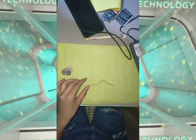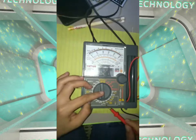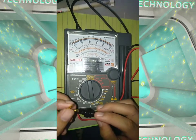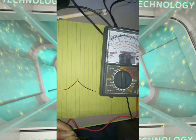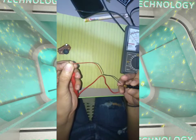So now our multi-tester is already at times 1. We are going to calibrate this multi-tester to see if it is at 0 ohms. Yes, as you can see, it is still at 0 ohms. So now we are going to test this wire, from here to here.